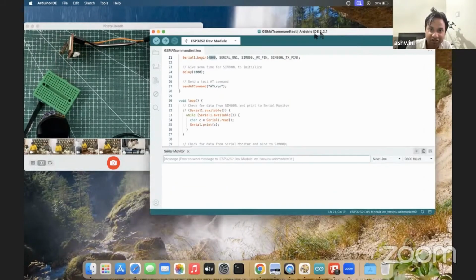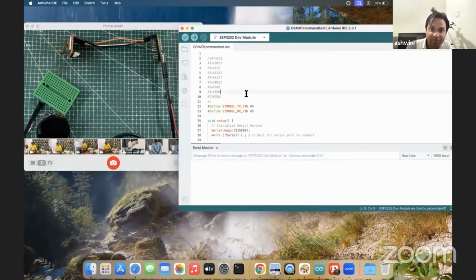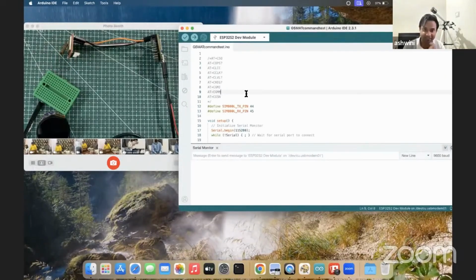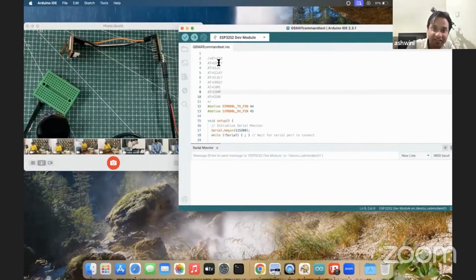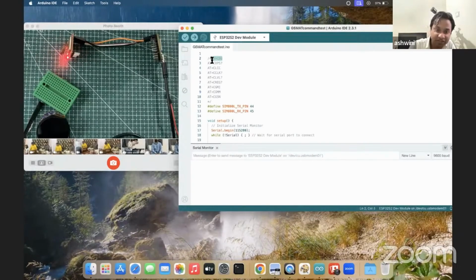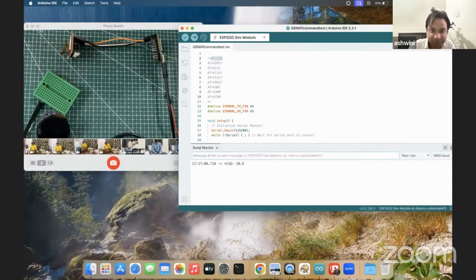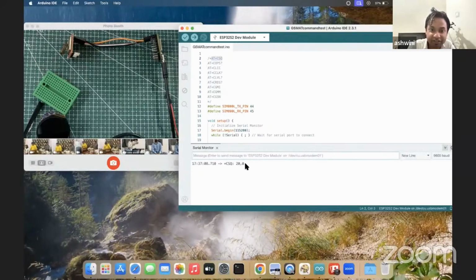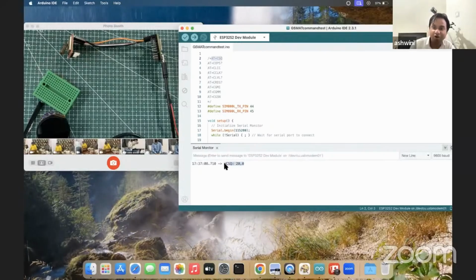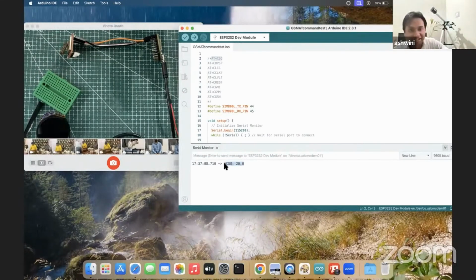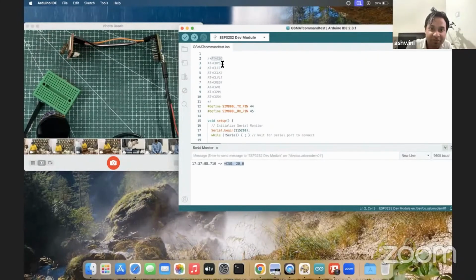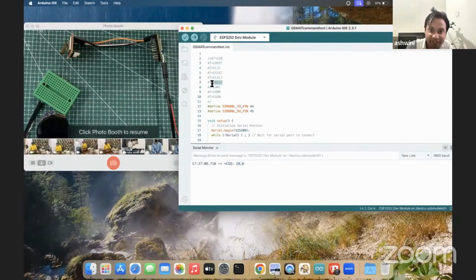when you open this, these are the basic AT commands that we can use to check different things. Like this will tell you certain things about the chip. When I send this AT command, it will tell you the volume level of the chip. If you want to increase the speaker volume, low or high, you can do that. Using this command, we will check the network status, whether it is connected to the network or not.